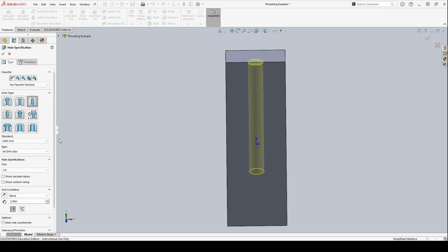So the 2 that I'm going to talk about here, I'm only going to show one of them, but we have our countersink and our counter bore, depending on whether our screw has a top that looks like so, or maybe like a button head or a flat head, where we're going to want the counter bore such that when our screw goes in, it is going to sit level with our overall object that we're screwing our screw into.